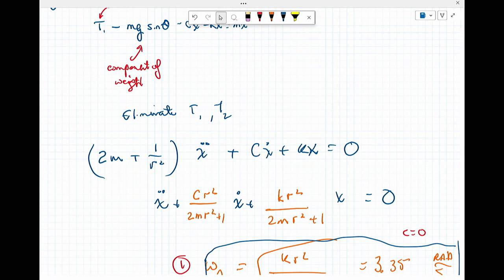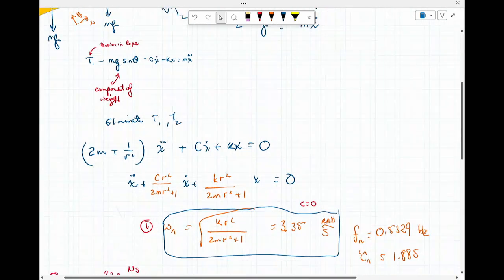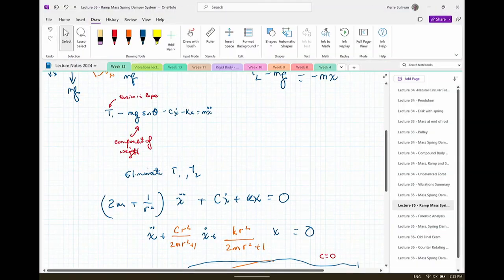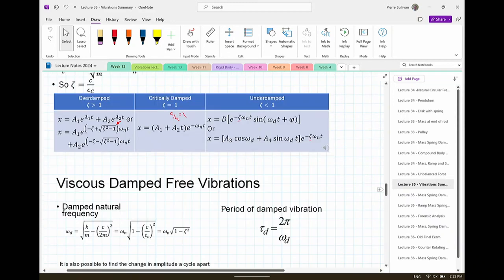And so that's your omega n squared, and that's your zeta. Nice. I do like Craig and Merriam better, in the sense that I like this form of the equation and the solution, particularly the fact that once I know what zeta is, I know what my solution looks like, and I can always solve it that way.